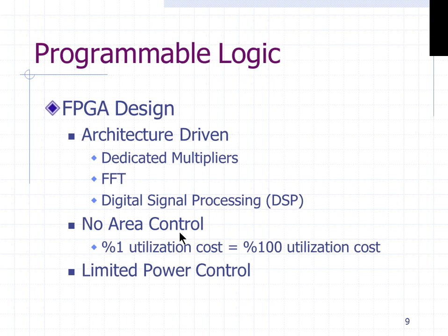So typically, total power consumption will be divided into static power and dynamic power. Right? Static power is related to leakage power, which you cannot really control. Dynamic power is related to your design and design frequency, design voltage, and some other factors like capacitance and other things. But operating voltage, operating frequency, and the logic of your design are factored into dynamic power calculations.